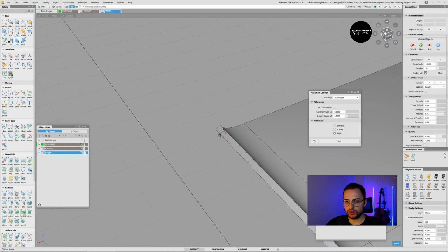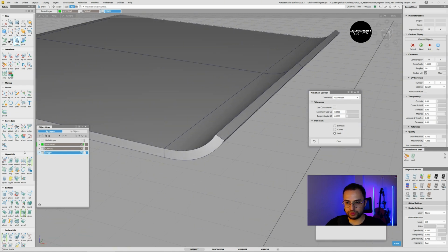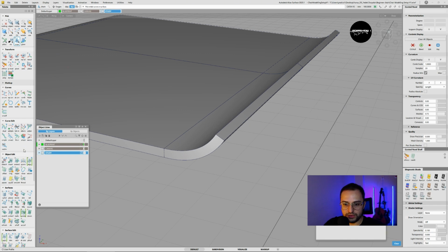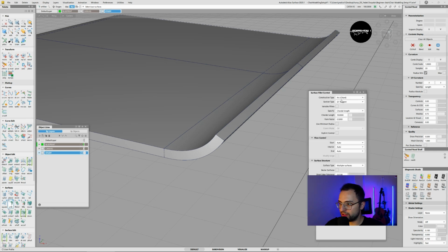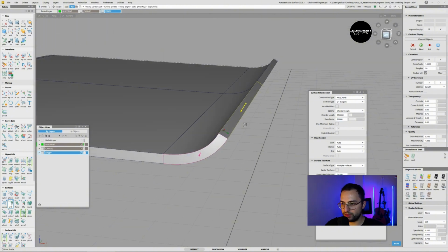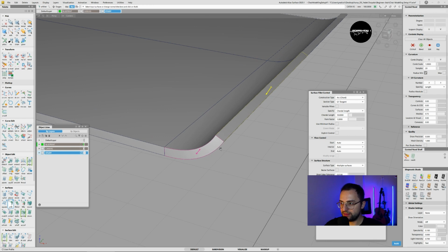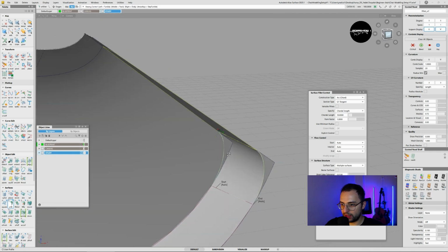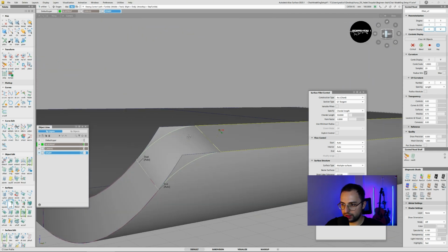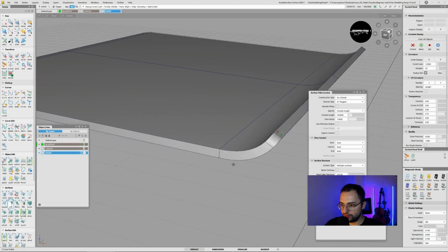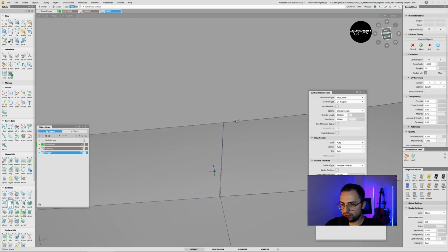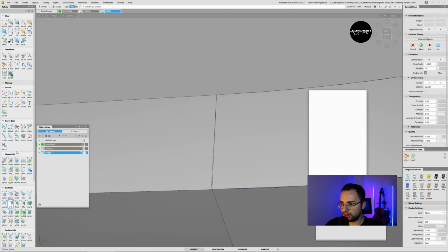So in order to operate the fillet tool, we can come here under the surface. There is a surface fillet tool, make it chord and G1, form factor leave it as 1, and select 2 of them. These arrows indicate which direction the fillet will be bent. Hit build, and we have our fillets over there between. I guess there is a continuity issue over here. I will be aligning G1.